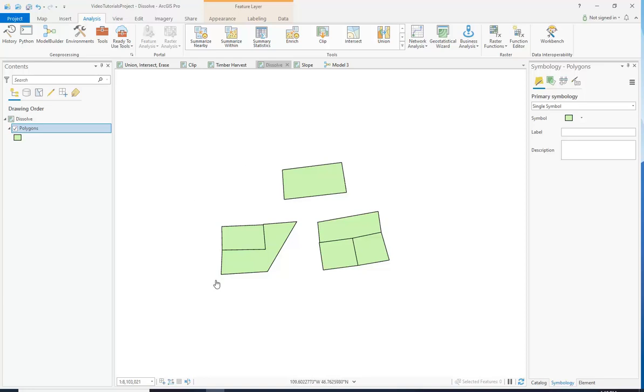Sometimes it's a little tricky because, if you look at these little squares over here, maybe this one over here is smaller than 10 hectares and this one over here is also smaller than 10 hectares, so they don't qualify for cutting. But this one is actually right next to this other one, and if we add them together, they probably are bigger than 10 hectares. So what we need to do is dissolve all these little polygons that are right next to each other so we can calculate the total area of those places.